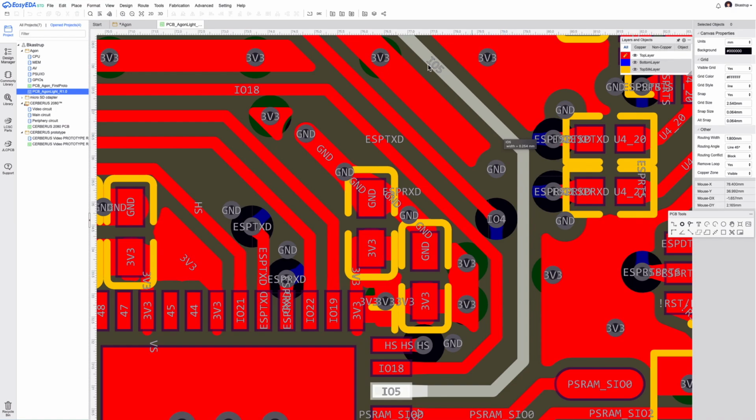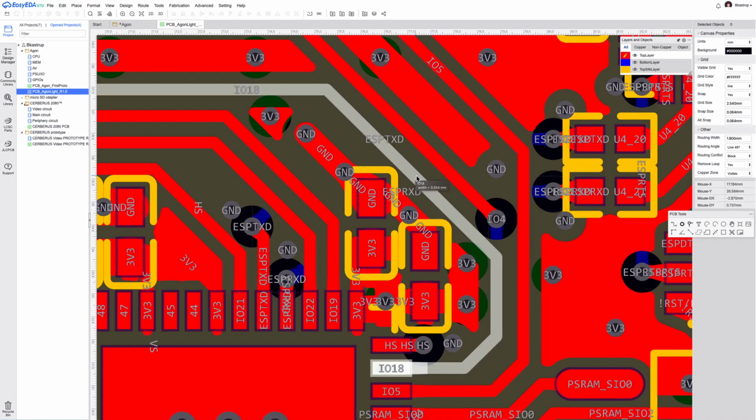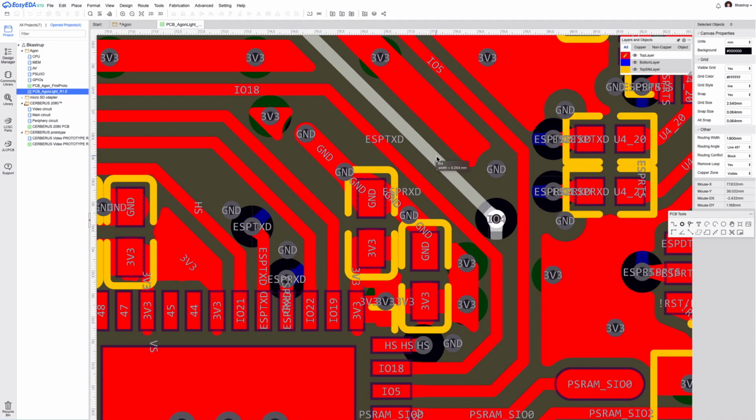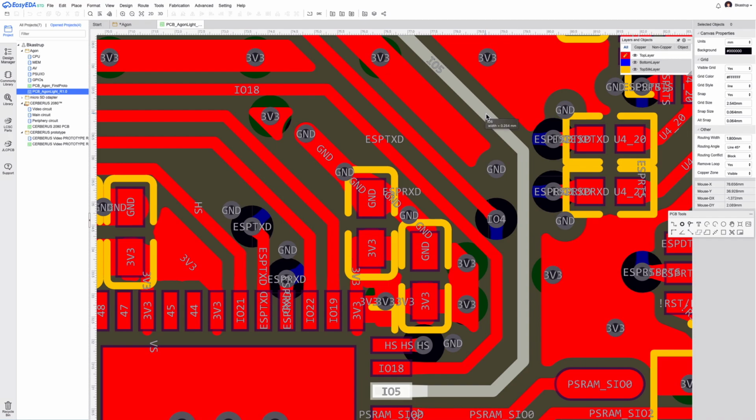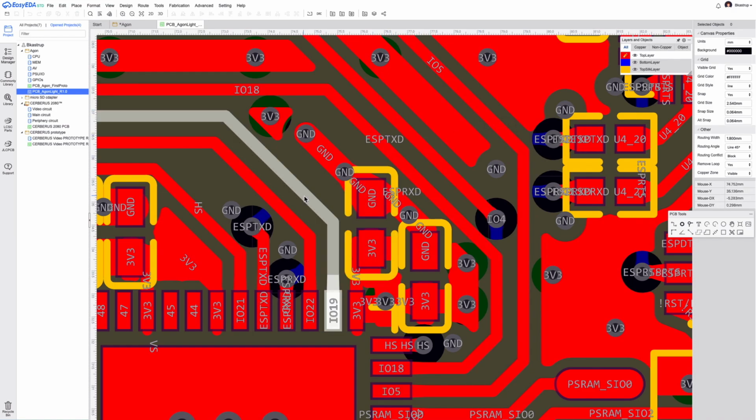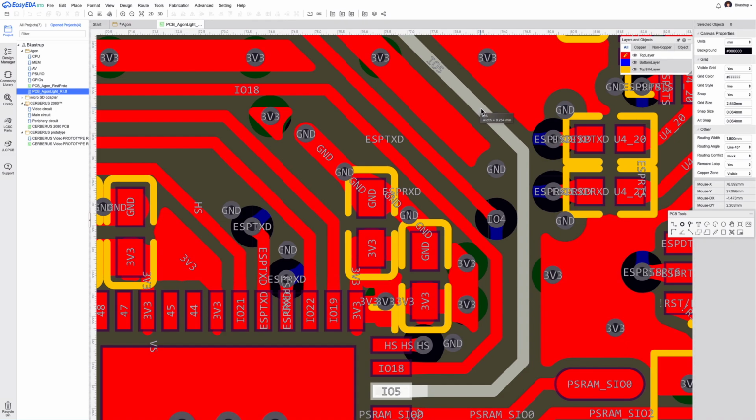And by coupled, what I mean is that when current flows through any trace, it produces electromagnetic field fringes. And what you want is that those fringes remain very small and very localized, because if they spread out, they will interfere with the other traces around. And then you get crosstalk, which you don't want. It's a form of interference. So to keep the field fringes very compact and not allowing them to spread, you put a ground plane or a VCC plane right underneath the signal traces, so they couple vertically downwards to the plane underneath, as opposed to coupling sideways to the neighboring traces. So that's why you want a ground plane underneath as the reference plane.